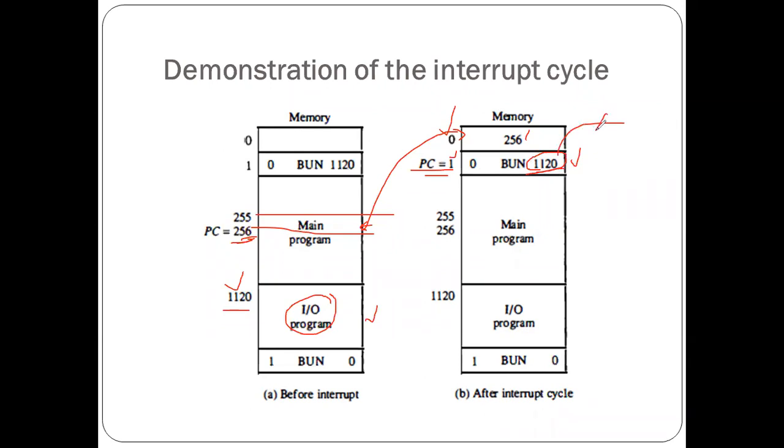Don't confuse this with 16 bits. They are using octal addresses, so each digit is 3 bits. 4 threes are 12 bits only. The remaining 4 bits specify the opcode, followed by the I bit. And why is this I 0? Because at this particular address you have your ISR program.